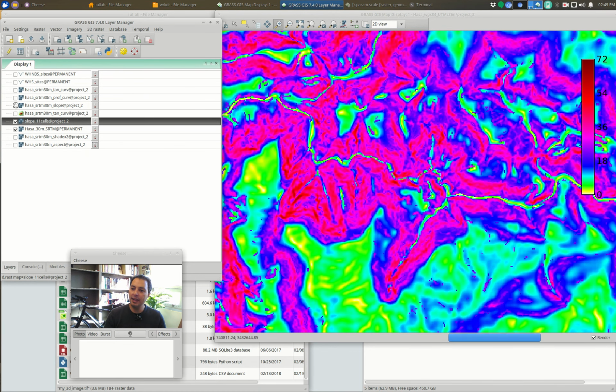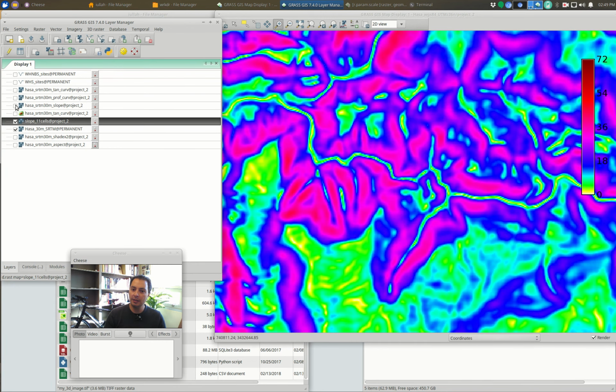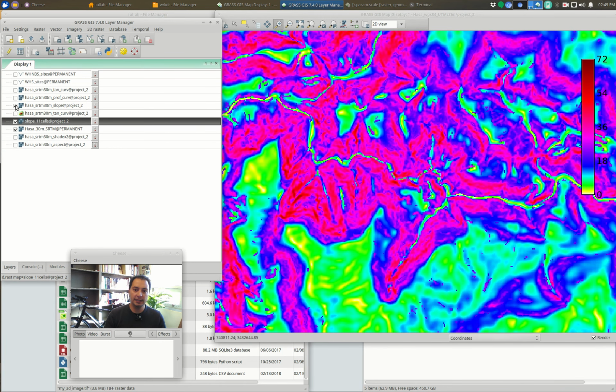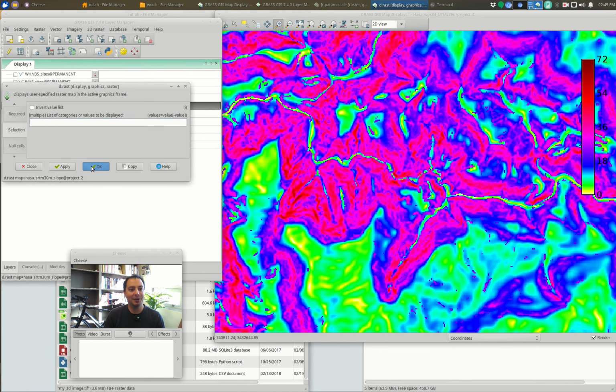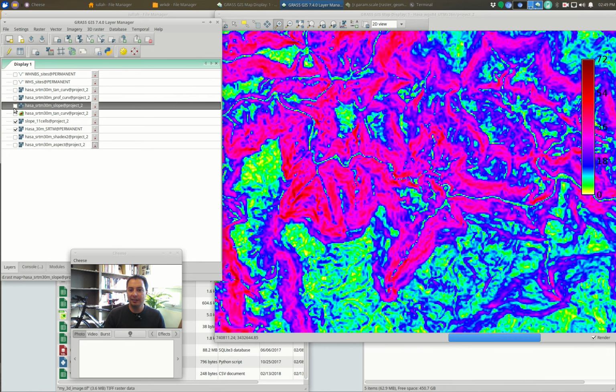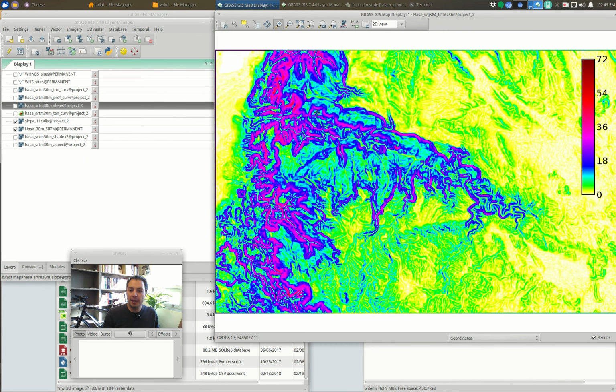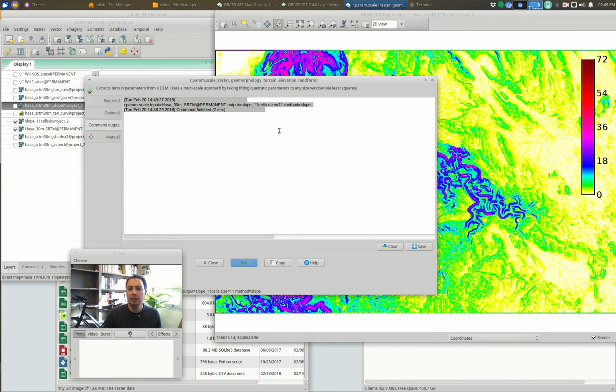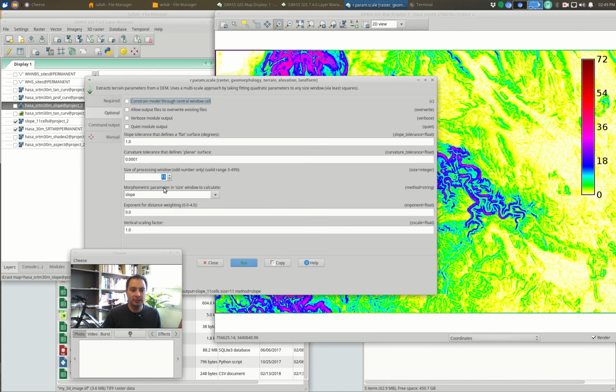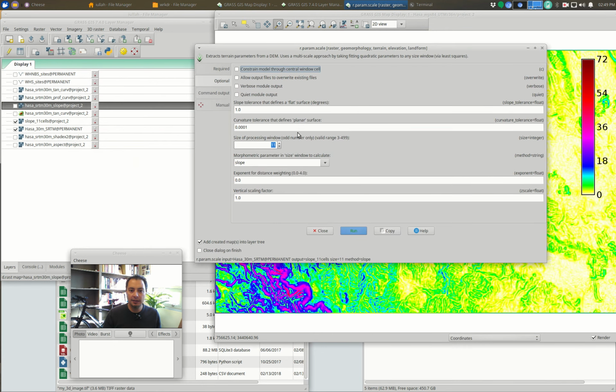You see the values are actually different. They're changing between them because of this, right? Did I have this thing still set to 2200? Yeah, okay, sorry. Look at that, right? We're basically seeing less detail, right? Less detail. We're blurring it. So we're looking at a larger, more macro scale of slope. Now that's really interesting. I'll go back to my previous zoom. So whatever we set in terms of our neighborhood size over here, that is going to set the scale of the analysis that we want to do.